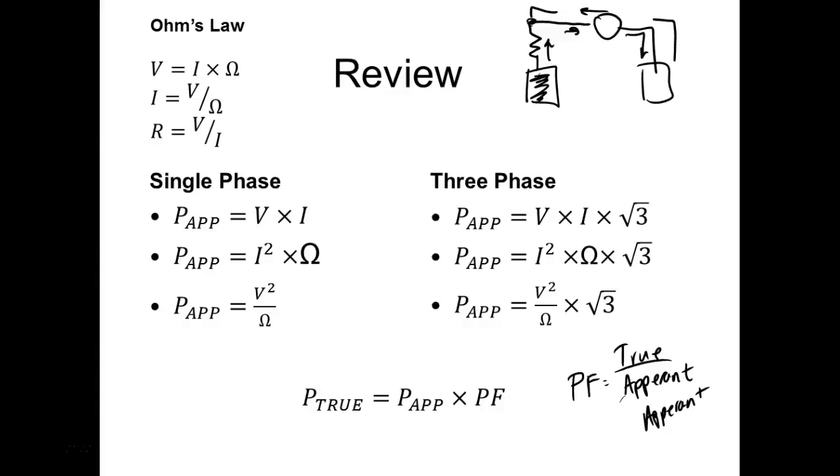So we have to worry about this in AC. We don't have to worry about this in DC. When we get into three-phase power transmission, remember, in three-phase your power is spread out over 3 wires. But they're not equal. So if I measured the current through here and the voltage between phases, I would get the power being delivered by 1 conductor, but the power is being spread out over 3 conductors.